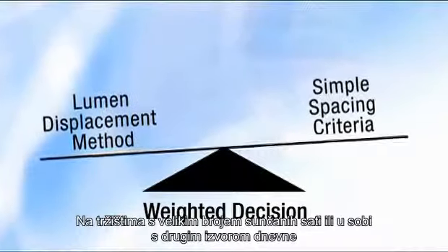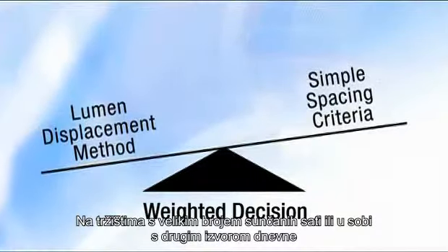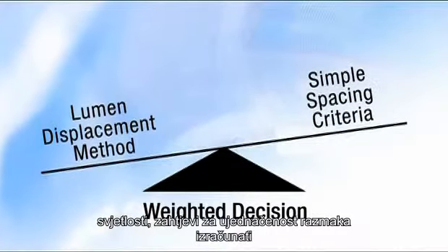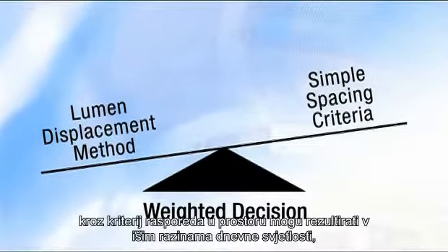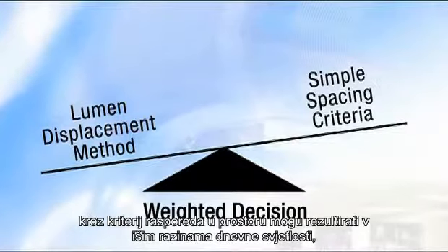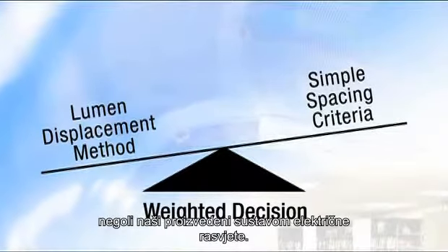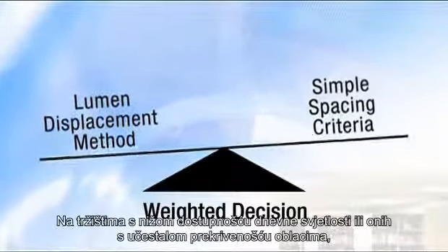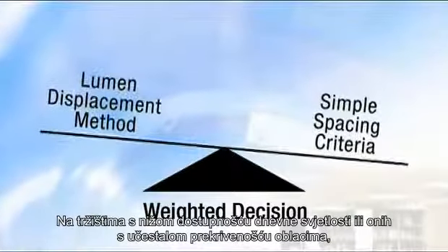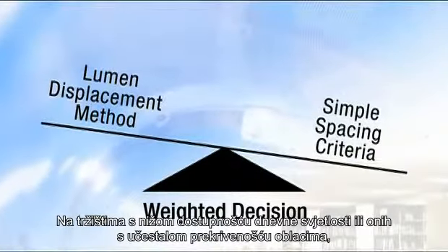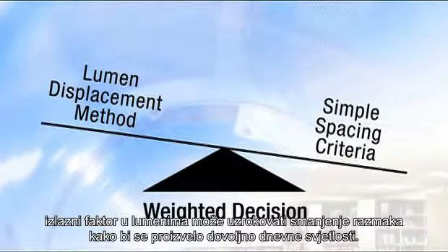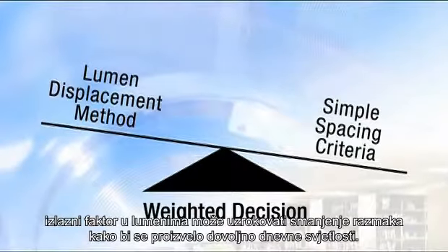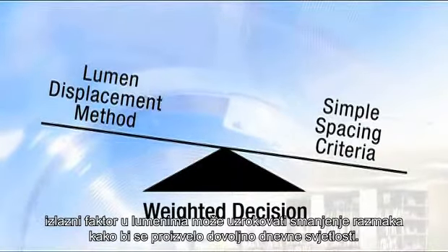In sunny markets, or in a room with other sources of daylight, spacing uniformity requirements calculated through the spacing criteria may result in higher daytime light levels than are produced with the electric lighting system. In markets with lower daylight availability, or those with frequent cloud cover, the lumen output factor may cause spacing to decrease in order to provide sufficient daytime light.